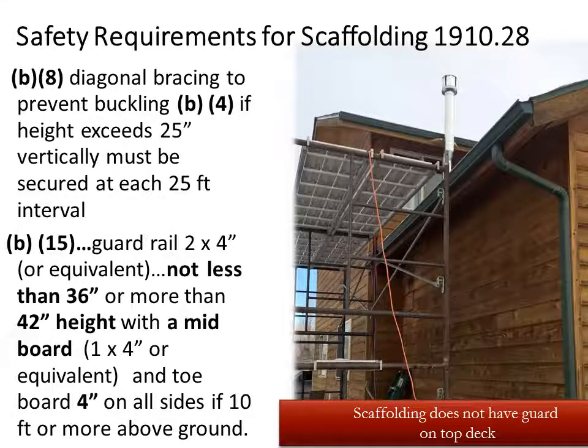So cross bracing at every 25-foot interval. If we're greater than 10 feet above the ground, we need to have a railing in place.